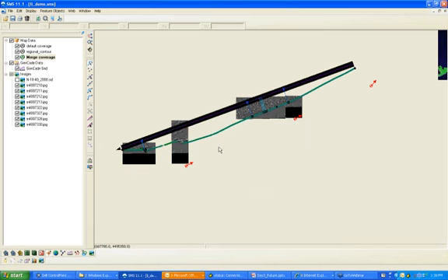One of the reasons that we have inconsistent wave values is because we don't have any waves yet in our Gencade grid. We've just entered them in the conceptual model, but the Gencade grid has no idea that we've entered that. So once we go back and reconvert to our 1D grid, that error will go away.